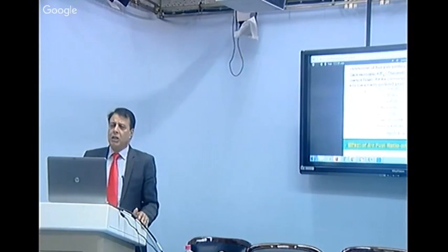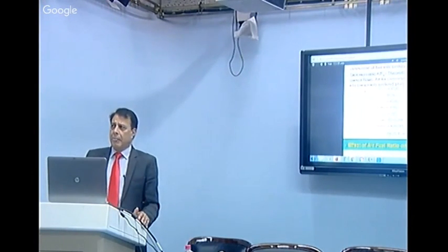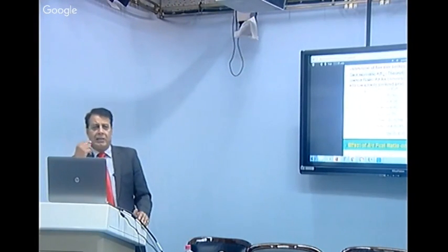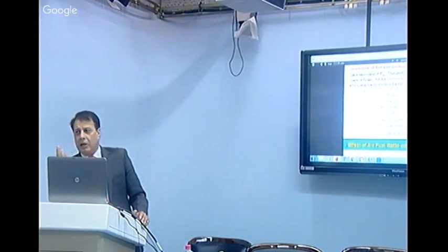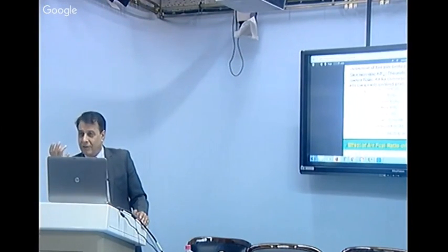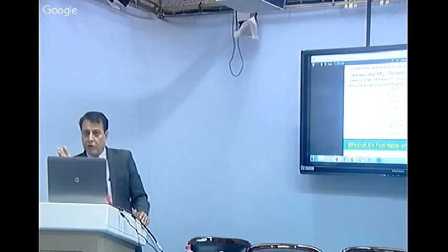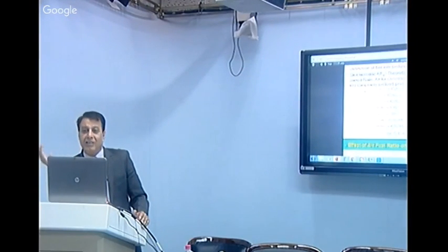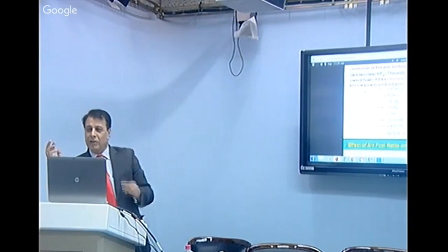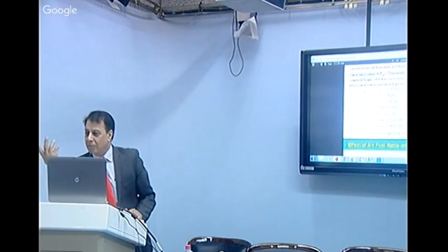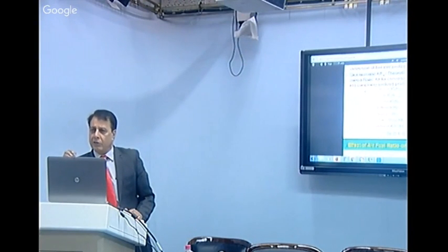Experiments show the dust holding capacity. I can give you a typical example of the Alto 800cc. The dust holding capacity is around 100 gram of dust, and you can clean this air cleaner after 10,000 kilometer, but we advise every 5,000 kilometer, because it depends upon the environmental condition also. Suppose somebody is running the car in Rajasthan where dust is more, somebody in Chandigarh, where the dust may be comparatively less. So it depends upon the environment, but generally it should be cleaned after 5,000 kilometer.